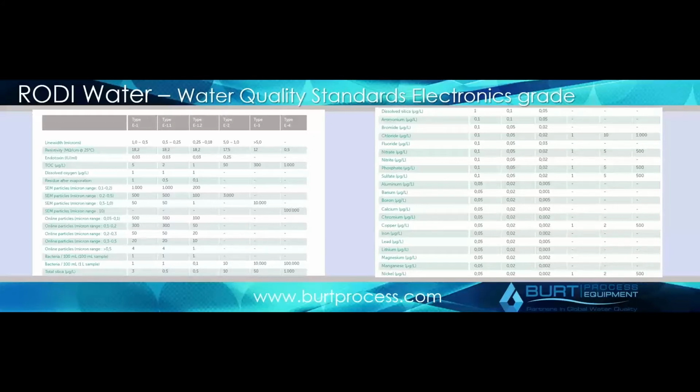It does get a bit tricky beyond that. Very often for research applications, they'll basically design that based on their processes. If you really don't have a good idea of what that is, in a laboratory or academic setting, it really comes down to what type of building you're trying to design. If it's more of a healthcare or medical application, you're looking a little less at resistivity and conductivity, and a lot more at things like bacteria or endotoxins that might push you more to an ASTM type 2 system. If it was geology or chemistry, maybe more ASTM 3 or ASTM 1.